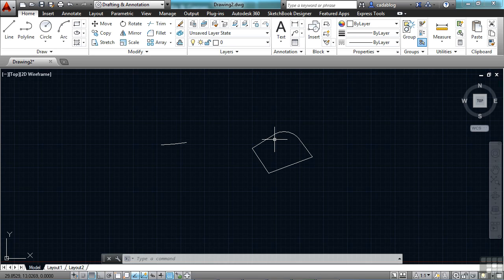Another thing that you can do is use the CONVERTPSTYLES command. That's a long system variable and it's a command, but it lets users convert the current drawing to either a named or color dependent plot style. That's just a different way of managing your layers and line types and layer colors and line thicknesses when they print. If you're going to use a CTB file or an STB file, this is just something that will do that change for you on the fly.